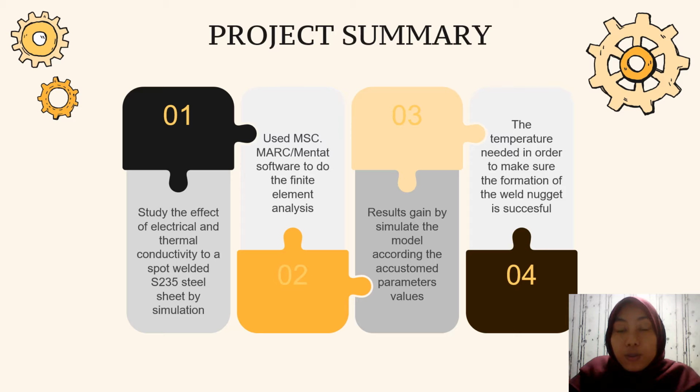The software used to do the finite element analysis is MSC Marc. The result is gained by simulating the model according to the custom dimensions and parameters of the electrode and steel sheet. So there is a certain temperature that is needed to ensure the weld nugget is formed nicely.